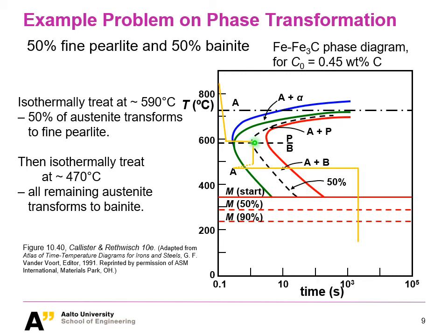They are still there. But before they do anything, you just quench it. You quench it to an even lower temperature right here, so around 500 degrees C. And by quenching, I think you should keep in mind, you will not have any phase transformation by diffusion.